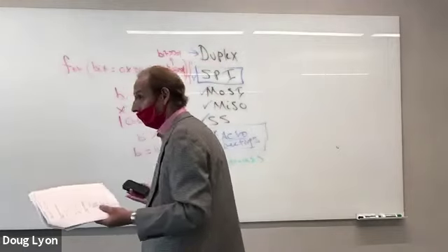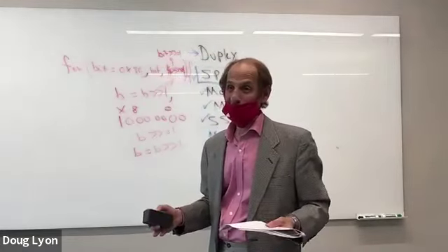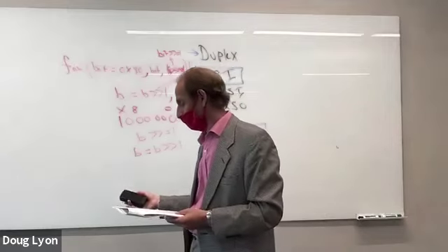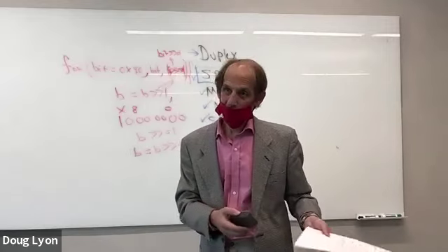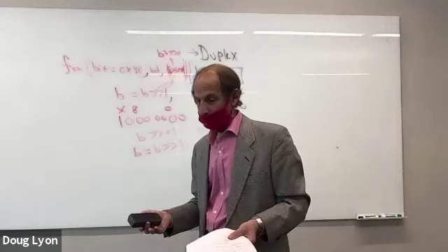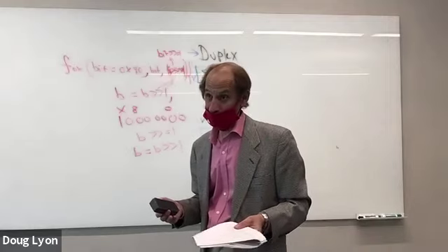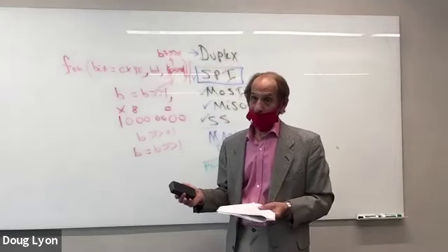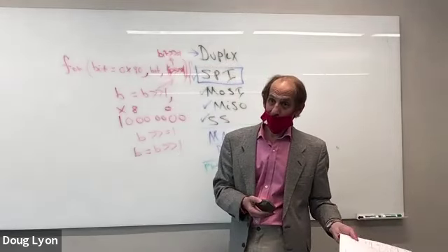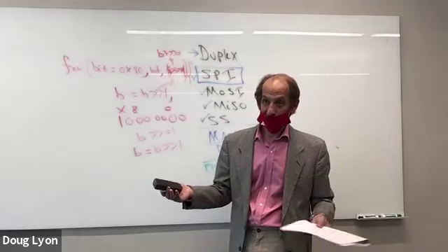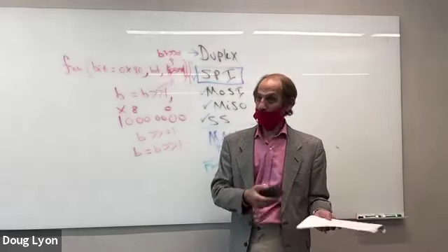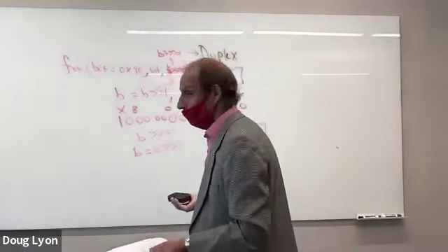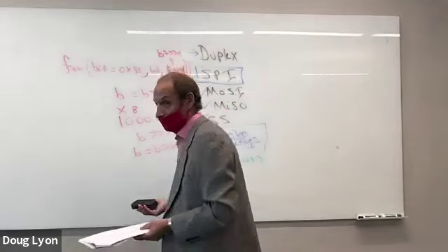And a lot of times they don't even care that you're using an Arduino. In fact, they don't want you to use the Arduino, they want you to use their products. The Microchip products are not the same products as Atmel products. Atmel products, that's the 328P, that's your Arduino Uno. Microchip makes a DAC. They want you to use the PIC. The PIC microcontroller is a Microchip microcontroller. They don't want you to use Atmel. They're not going to cater to Atmel, but they'll give you a data sheet, and if you want to use their device on the Atmel processor, you've got to figure it out. And that means you've got to read the data sheet.